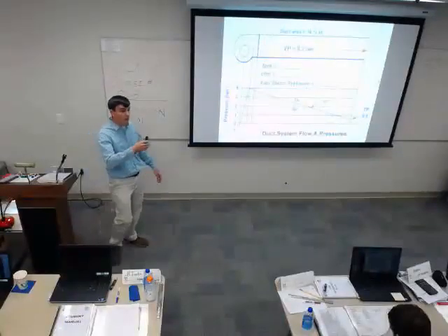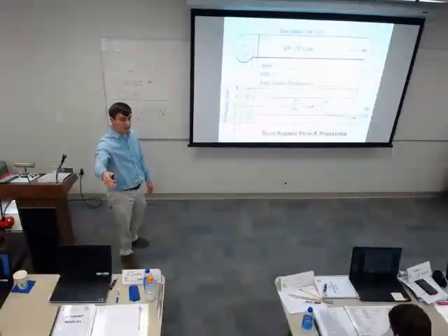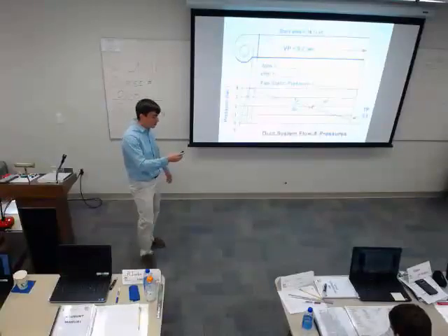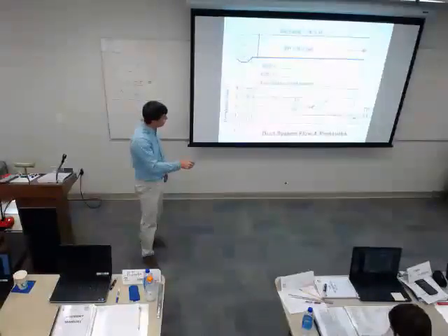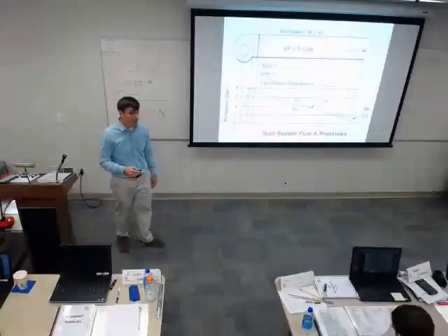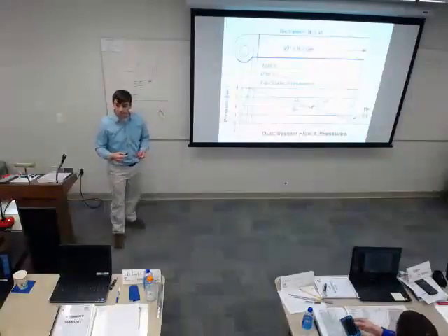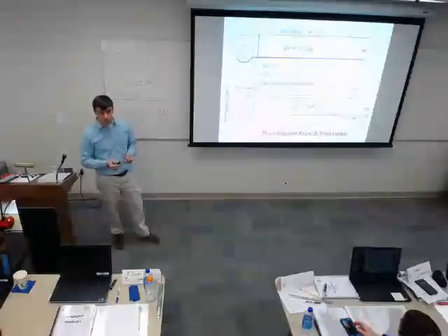And if I were to measure the velocity pressure at any point, it would be the same. But I am losing static pressure. The resistance of the duct is causing me to lose potential energy. Static pressure is our potential energy. That make sense? Feel free to ask questions.